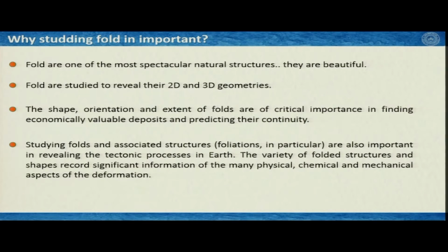Therefore, if you see different parts of this fold in different places, it is very important that you construct their first 2 dimensional and then 3 dimensional geometries, and it is not only the field work, you have to collect the data like dip, strike, trend, plunge of related structures, and then you have to plot it on the stereo net, and then you can construct the 2D and 3D geometries. This you must learn from your field studies.